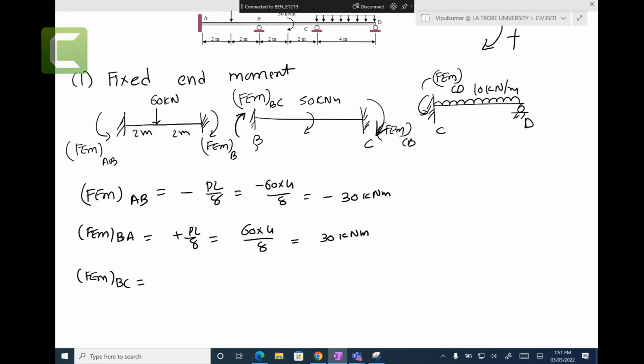If you have an M going here, you need to have those reaction moments, or what you can say is that for equilibrium of these members, you need to have this. Because you can see this one going which way? Anti-clockwise. So here they should be, because all those joints are in equilibrium. All these members are also in equilibrium. You can see that 50 kilonewtons. To have these 50 kilonewtons, we need to have these clockwise moments going on those. Aren't they all going clockwise? This one. Oh, sorry. They are all going clockwise.